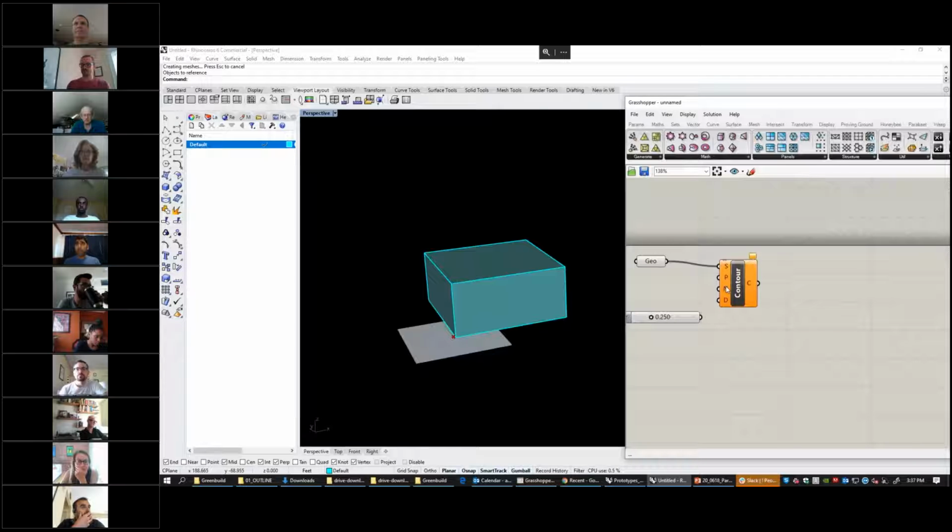It's just going to start at the origin, which is that red point right there. The normal direction right now is 0, 0, 1, an XYZ coordinate, so it's pointing up. So it's going to contour your object up from the base of the model, a set distance, which it doesn't have yet. So I'm going to plug this in there.